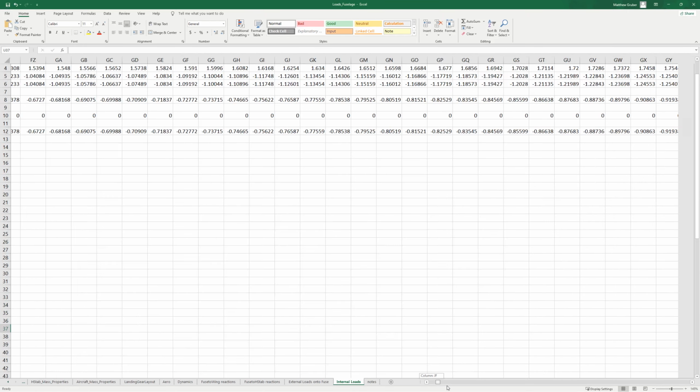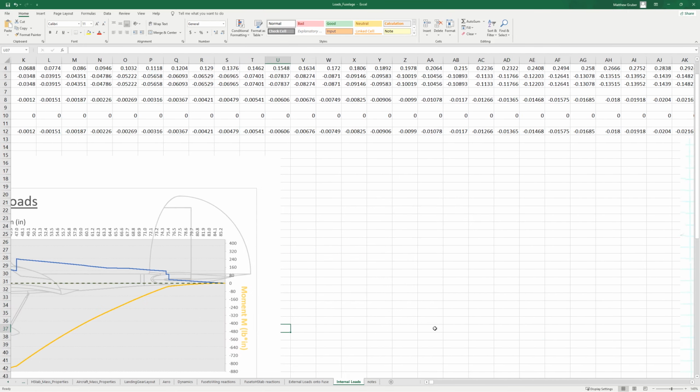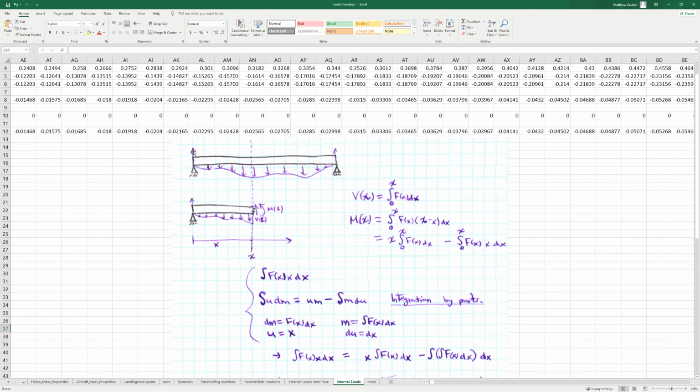You might notice here that if we look at the general free body of a part that we're going to do a loads diagram for, we generally have these reactions that we haven't calculated for. In our case, we didn't have any of these reactions because our case is not a supported beam. It's actually an aircraft in the air, or we can sort of imagine the main gear as a support, because in that case, that's kind of like a reaction.